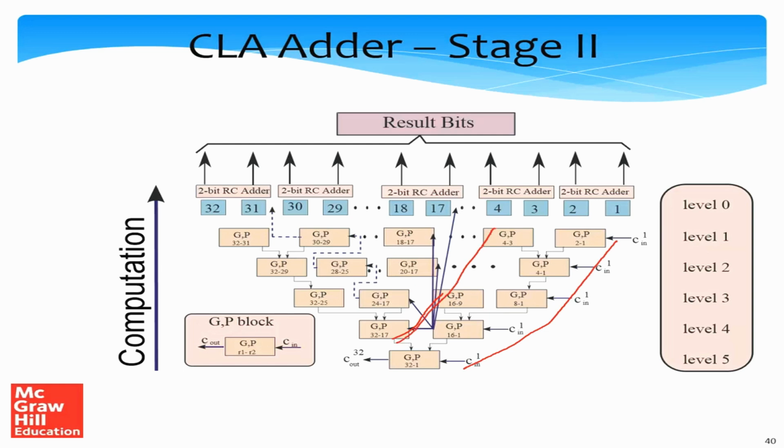So the front keeps on advancing, and all the blocks at the lower levels sort of keep on computing their carry. So basically within 4 steps, we were able to compute the carry out here. I'm sorry, the carry in at this point. So this holds true for all the other points as well, that within a maximum of 5 steps, the values of the carry input values of all of these adders would be there.